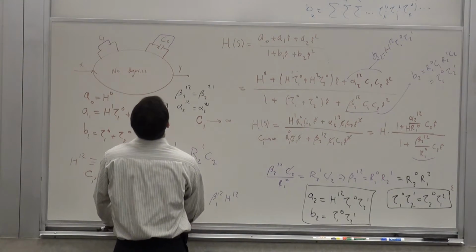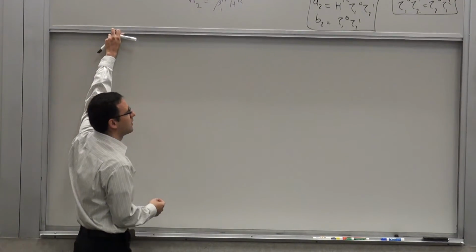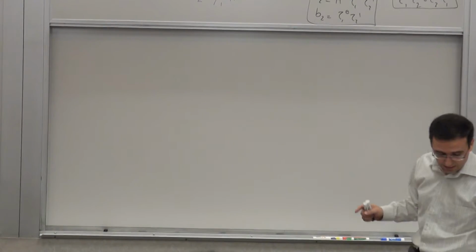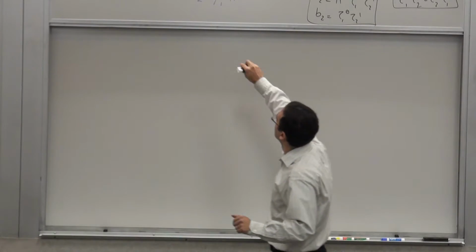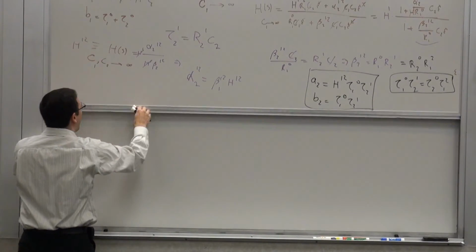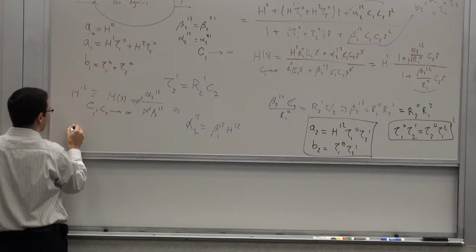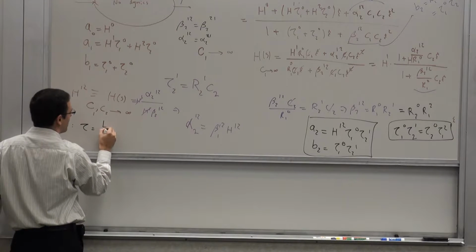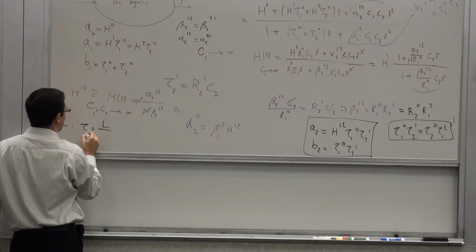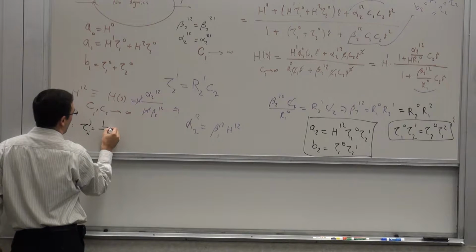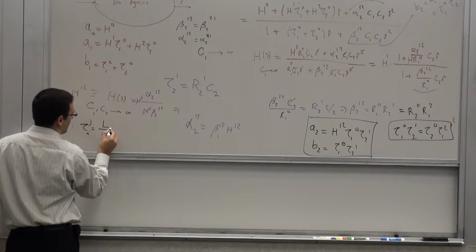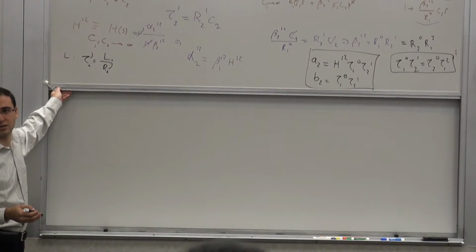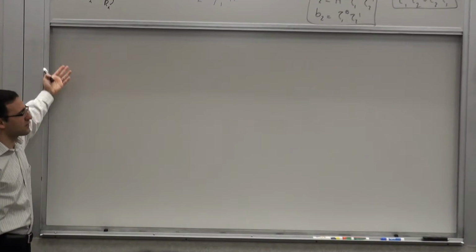So now, what do we do with this? Let's talk about a couple of examples. Let me just go over a few. And by the way, one more thing. If you have inductors, everything is the same. So taus, for capacitors, obviously, we calculate them. If you have inductors, then any of the taus would be basically the inductor over the associated resistance. So let's say, for instance, tau ij would be Li over Rij. Just instead of multiplying by the resistance, you divide the inductance by the resistance. Time constant is L over R. So it applies for both inductors and capacitors.